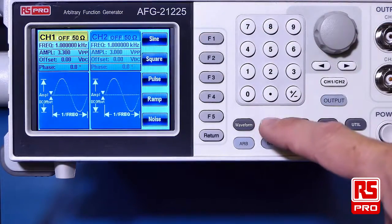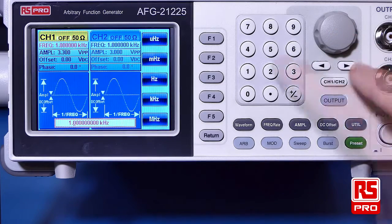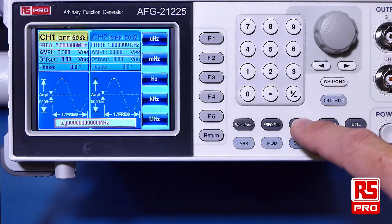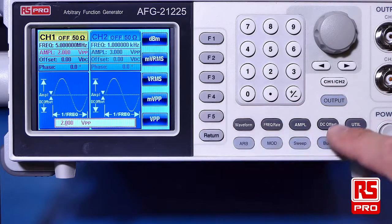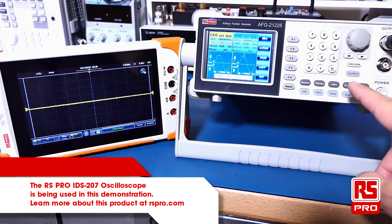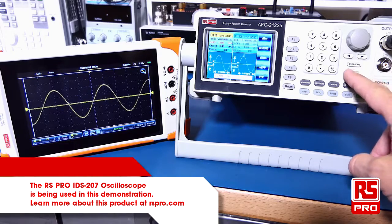In this case, we'll set the sine wave. We can set the frequency rate. This can be done either using the rotary encoder and the navigation buttons or via direct entry on the keypad. We'll set 5 megahertz. We can set the amplitude. We'll set that to 2 volts. You have the option to go and set a DC offset and the phase of the signal. Once all your parameters have been set, your signal can be output by switching the output button.